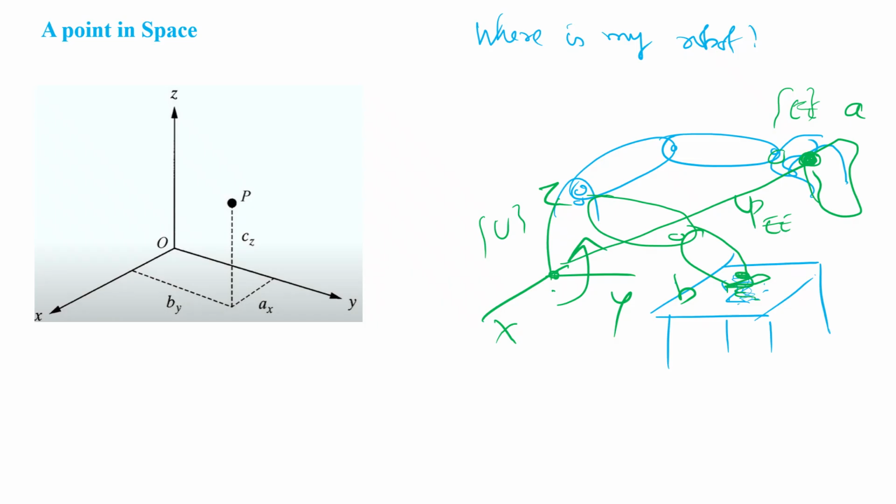So next one is orientation. How far it is rotated? Since it is a frame, it may have an x-axis like this, a y-axis like this, and a z-axis like this. We have to compare this x and this x, how far it is rotated. And then this y and this y, and this z and this z. If you compare this z and this z, they are 180 degrees apart. And if you consider this y and this y, they are like 120 degrees apart.